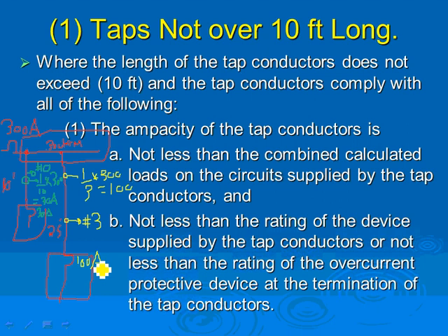So it's a 100 amp panel, I can't put more than 100 amp. But I can split these, say, into 3 or 4, 100 divided by 4, 25. I can split these into 4 25 amp circuit breakers in a panel. And that's okay.